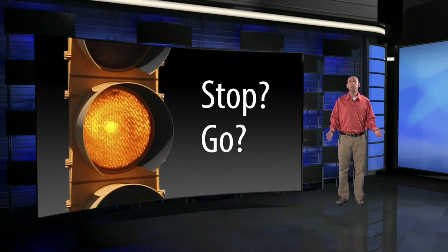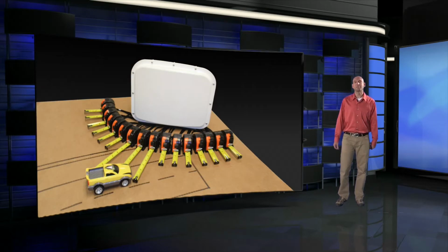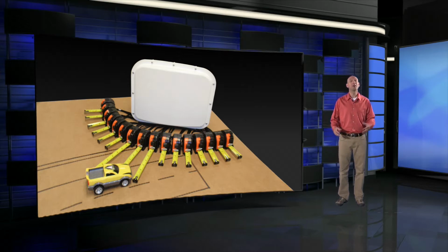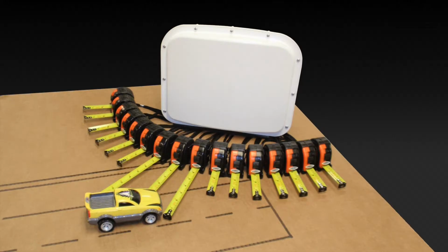So even with this unique feature, SmartSensor Advance does not provide any kind of an image of the traffic or of the approach to the intersection. So that then takes us to the next sensor, and the one that does create an image of the roadway. This is a multi-beam ranging radar, and SmartSensor Matrix is the only one of those in the market.